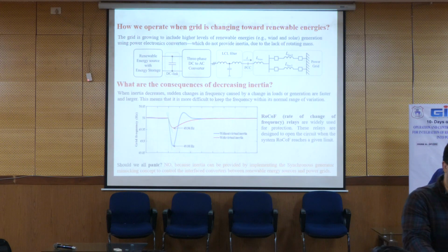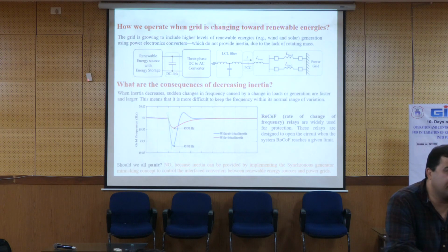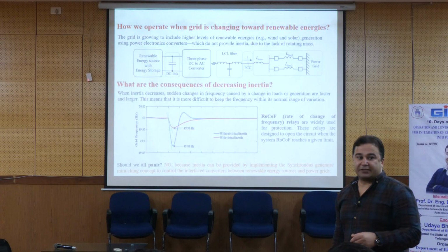Definitely we require a solution to provide inertia. That's why we are going to prefer energy storage devices. By using storage devices we provide the required inertia. How? Whenever a fluctuation happens, if supercapacitors are there, at the dynamic state initially those are more power dense devices. Whenever the fluctuation happens, they react immediately and sufficient energy is supplied by those supercapacitors.